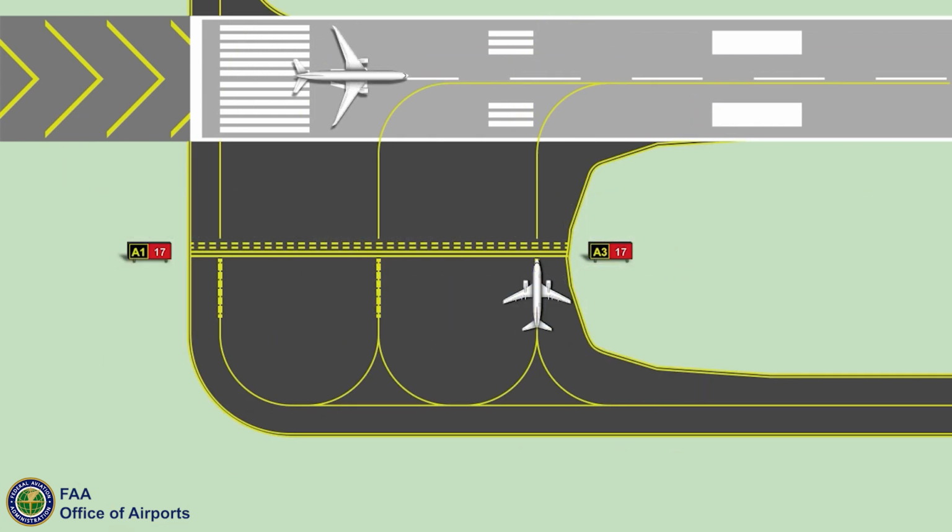Wide pavement areas at a runway intersection result in placement of airfield signs, marking, and lighting far from a pilot's view, thus limiting the pilot's view of critical visual cues. This increases the risk for pilot loss of situational awareness, particularly under low visibility conditions. The loss of situational awareness increases the risk of a runway incursion and risk of wingtip conflict due to pilot judgmental taxiing of aircraft.